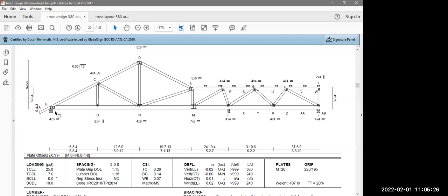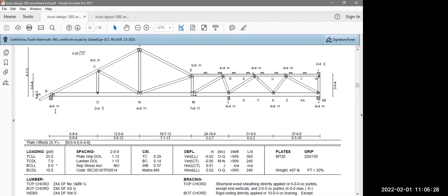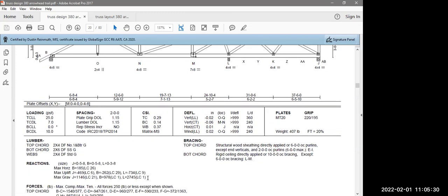And so what I've got to do, for J, B, and L, is look down here at these reactions. That's kind of a key word in engineering, the concept of a reaction. So notice I'm looking at gravity. And these are kind of like that rocker support a minute ago. They're just sitting on top of this. So the only force that these walls are producing is just basically up. J right over here at the right.